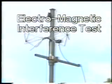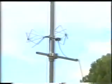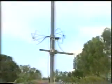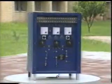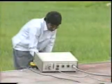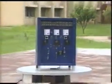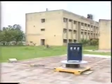Electromagnetic interference test. This test is conducted to find the electromagnetic interference produced by an equipment while in operation. The equipment to be tested is placed on a rotary platform which is rotated by 10 degrees in a step so as to measure electromagnetic interference from all sides of the equipment.